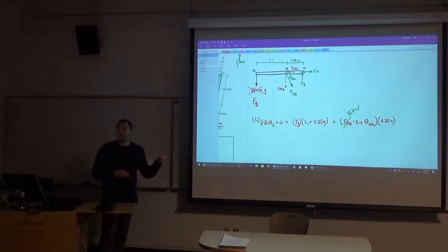Okay, so that's the relationships, and generally speaking, you're almost always going to have to resort to summing the moments about some point, and I recommend doing that early or first. It won't give you the wrong answer if you started by summing the forces in the y. It's just going to give you an equation that you wouldn't have enough information to solve for, or you would need a couple of simultaneous equations to get to the same answer.